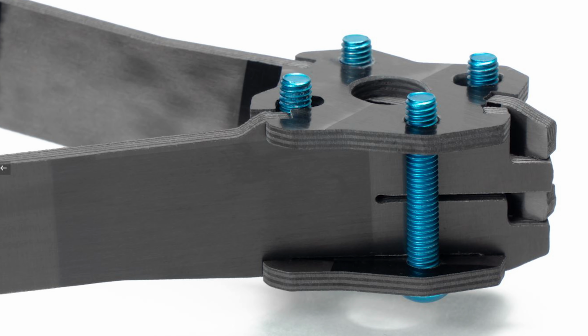This is a very annoying issue that I have had to deal with, and it's the reason why you don't see a whole lot of designs where carbon pieces fit into other carbon pieces. So if you're trying to make a 90-degree angle on a carbon sheet, if you want to have a 90-degree corner, you can't, because you have to cut this sheet with a round object.